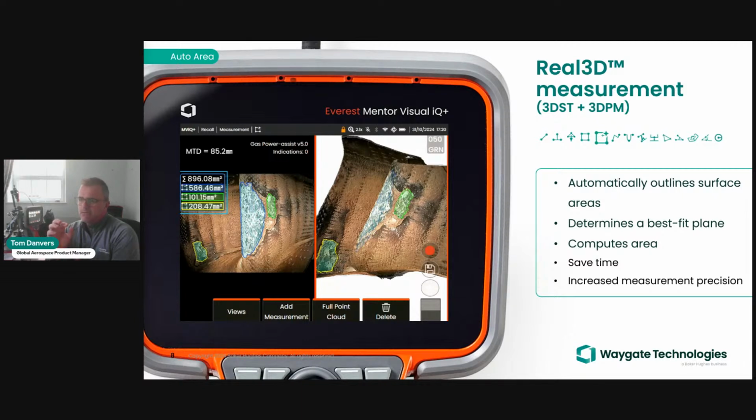We now have the ability to scan the image for texture or contrast. This is based on artificial intelligence, but it's not using the images that you will be processing on your borescope. Here is a picture of an HP turbine nozzle guide vane. With the use of the model in the background behind auto area, it's able to identify areas of high contrast.